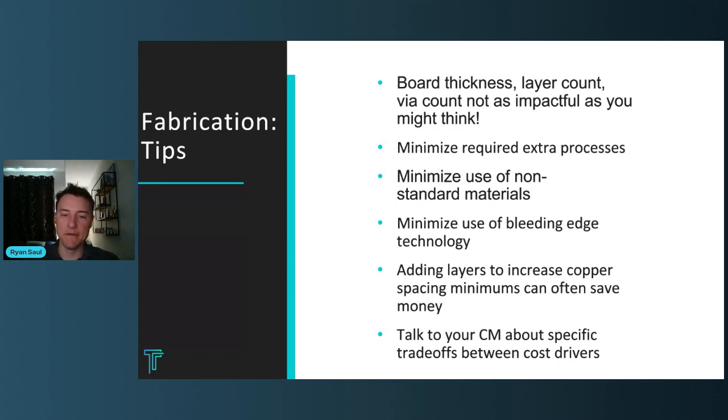Real quick, this is where your board has to be built up in several separate laminations. For example, if you have a buried drill pair, you will always have at least 2 lamination cycles. For example, an 8-layer board with a 2 to 7 drill pair. That means 2 to 7 will be built up as a 6-layer board. It's going to be etched, laminated, drilled, plated, just like it were a full 6-layer board. And then they're going to laminate on layers 1 and 8.